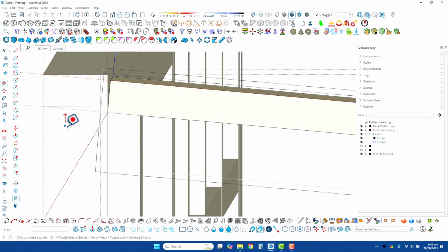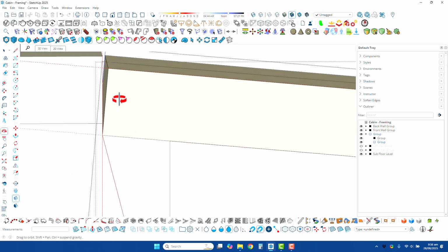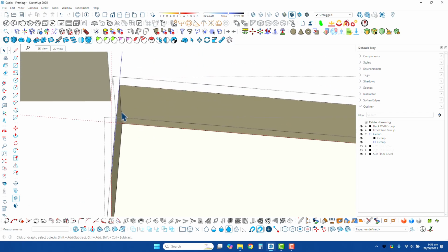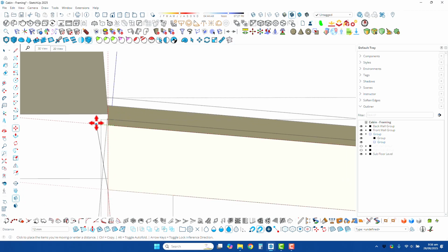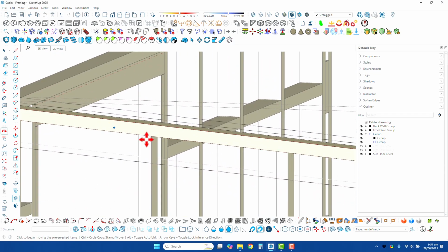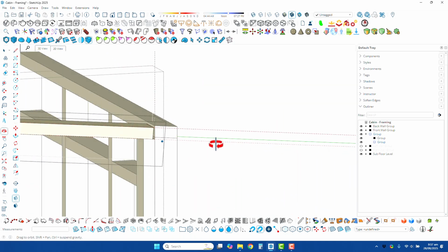So now you go back to your cursor. Sorry, I'm on the verge of having a coughing fit and trying to hold it back. Select the line, select the move tool, and you can move this piece of geometry. The safest way is to locate that guideline, press and hold shift, and then just snap to that vertical face intersection which is there. Don't worry about the step. We said earlier that the walls were all different because I just threw this together for the tutorial.